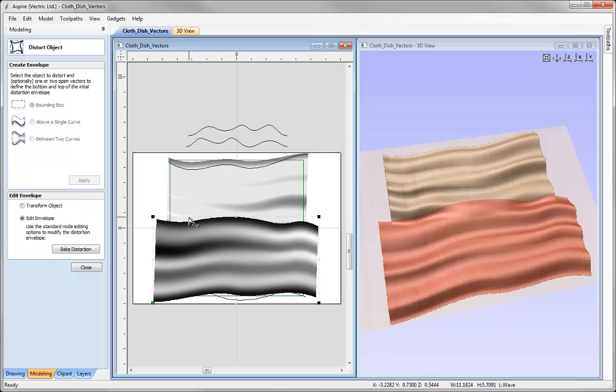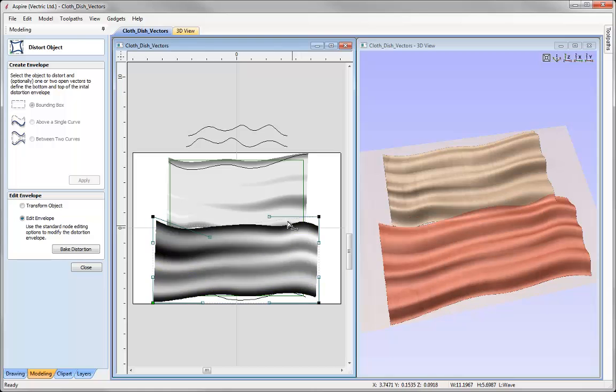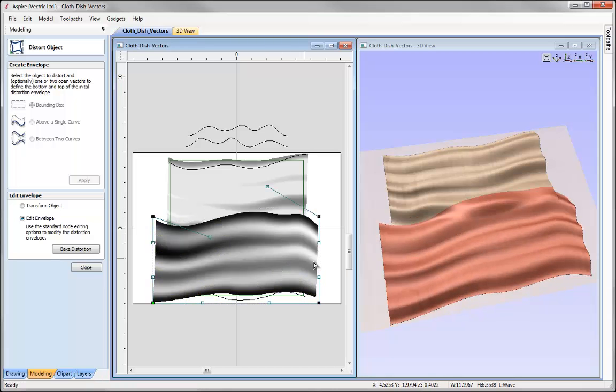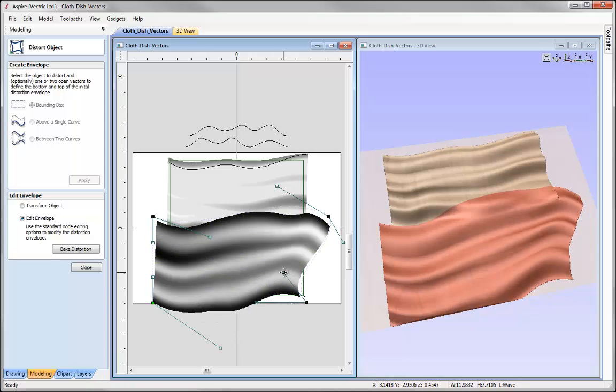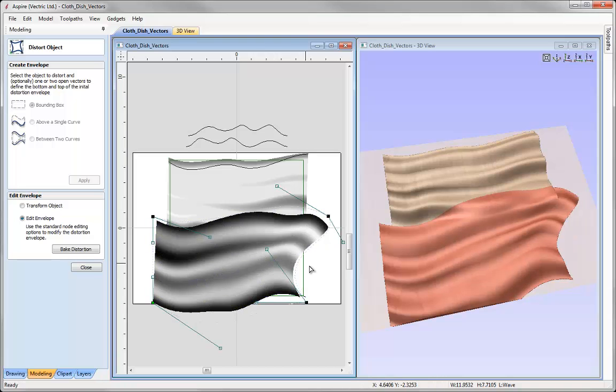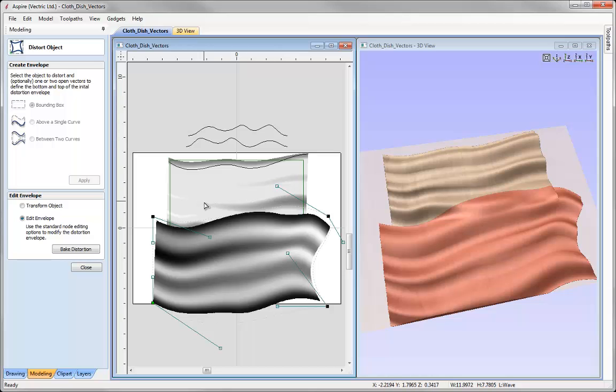Now I'm going to hover over the edge, I'm going to hit B on the keyboard to add in Bezier spans on all 4 edges, so you'll see the control points appear there. And now we can start to play around with what this shape is doing. We can move the control points, we can move the actual main points in the part as well. And you can see this just allows me to create a different kind of flow and feel to the shape than the original one that we've got.